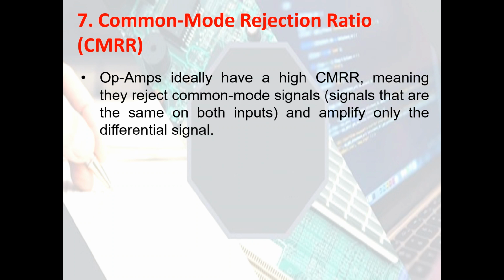As per the practical considerations, real-world amplifiers cannot achieve infinite CMRR, but a higher CMRR value indicates better common mode rejection. CMRR is affected by imperfections in the amplifier circuit, such as component mismatches, imperfections in the differential amplifier stage, and limitations in the op-amp's characteristics.